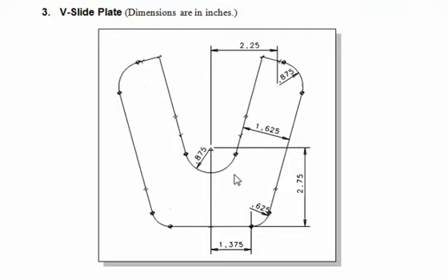The parametric sketching tools can be used to maintain these geometric relations. AutoCAD will display special symbols next to the objects when we apply parametric constraints. Using the parametric constraints and dimensions provides a very effective way to create drawings, especially when revisions and modifications are expected. So let's begin.